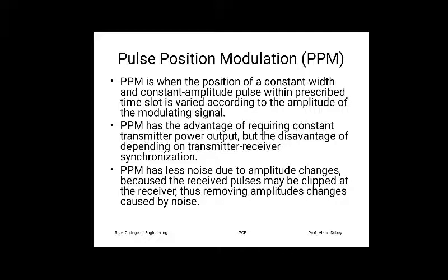The problem with the PPM is that it requires proper synchronization at the transmitter and receiver. Otherwise, if there is a mismatch in the synchronization, obviously the information regained will be different. PPM has less noise due to amplitude changes.